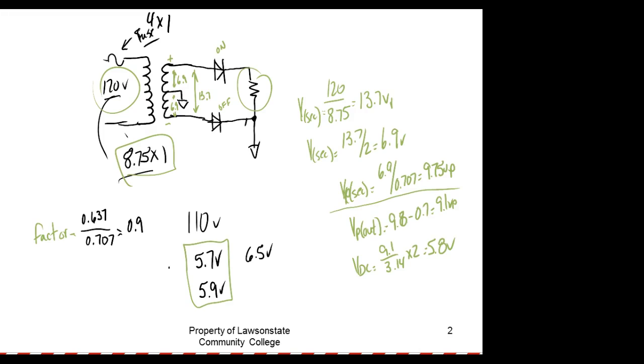So what they're saying is that if I got 6.3 volts on my primary, then my DC average would be equal to 6.3 times 0.9. What does that give us? And this is a pretty neat equation, but what are they ignoring? They're ignoring the drop of the diode. So what's going to happen? So this answer is always going to be higher than what we actually measured. So what do we got?